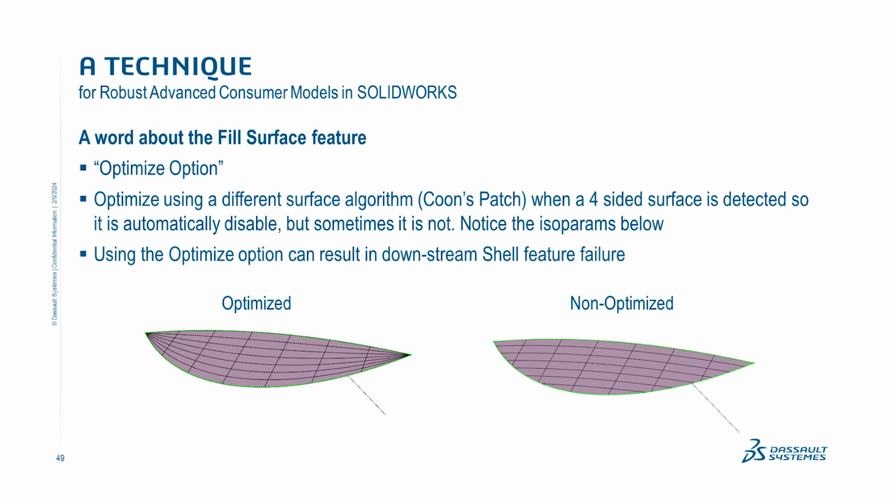If you turn on your mesh, you can see it building a surface, but out towards these endpoints it becomes degenerate because the isoparams are all converging on the first and second edge of the fill. If you turn that off, you get a different algorithm that solves for the isoparam direction independently of its surrounding tangent or curvature faces. That's what makes fill so powerful, and the right solution for 3-sided or 5 or more sided surfaces. Okay, enough about fill. Let's keep going.